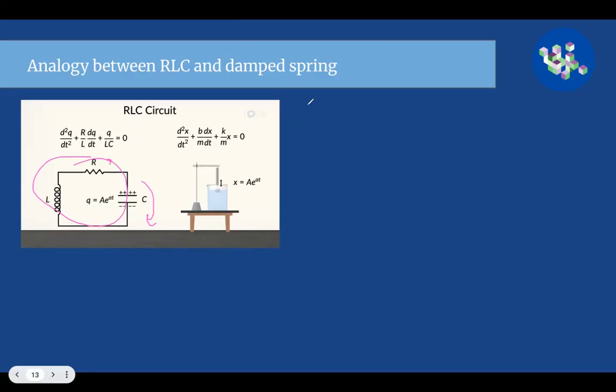So our differential equation will be something like, across the resistor, it's basically I times R, and then across the capacitor, it's Q over C. So I times R plus Q over C will be the total voltage drop across the resistor and the capacitor. But then we also have a voltage rise across the inductor, so we're going to say that equals L i dot.